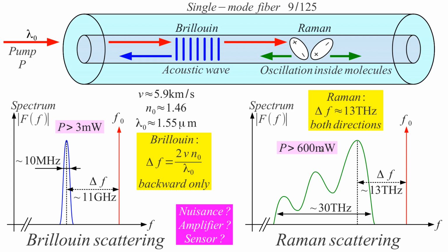Well, this can be done in a fiber, but here it's very hard to use connectors. It's very difficult to get lasers for this power level. So also with Raman scattering, you can make Raman amplifiers, also very low noise, also for long distance communications, but they are very expensive because the powerful laser you need is very expensive. It need not be narrowband. Raman may have reasonable bandwidth lasers.